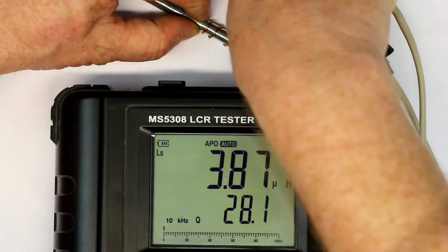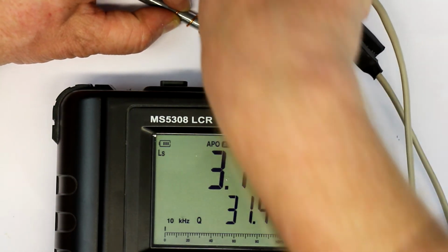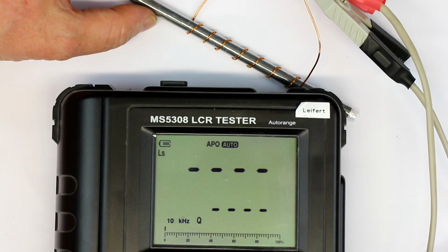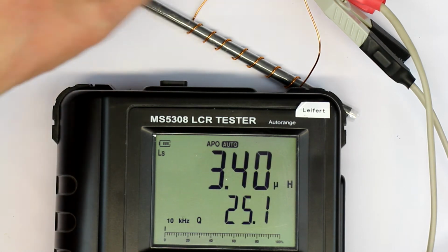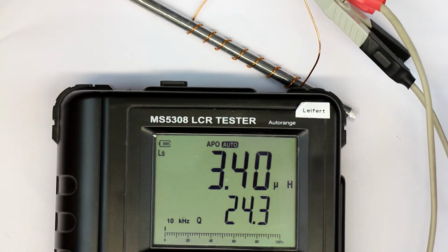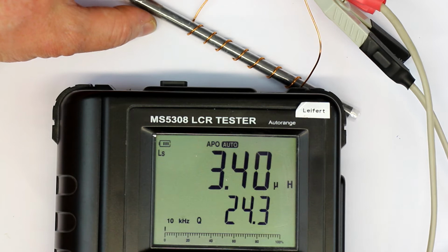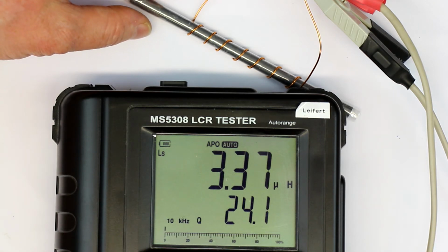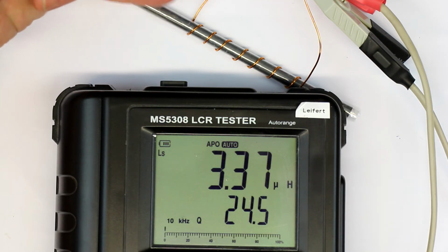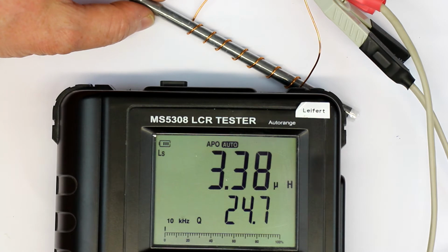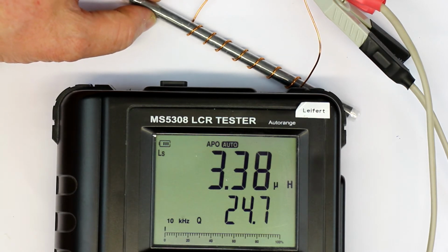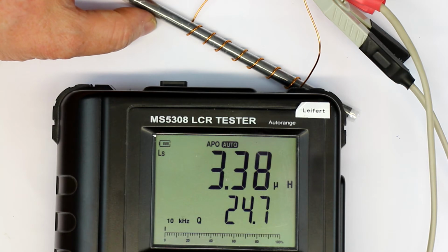Let's see if we see it now directly on the display. You can see that the inductance changes just by squeezing or drawing at the ends of the coil. And that's also another well-known method of fine-tuning the inductance of coils, no matter if they are wound on a ferrite-rod or in air, just to fine-tune the inductance or the resonant frequency of an LC tank circuit.